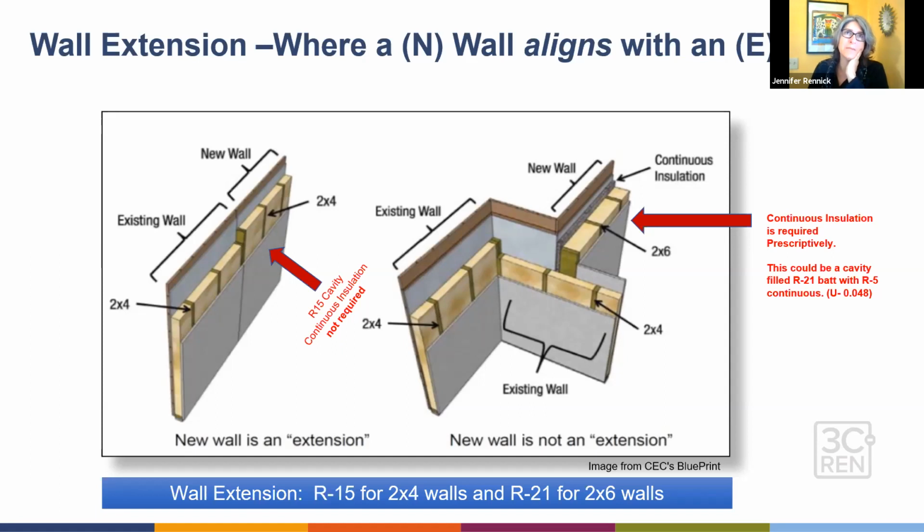And as a plans examiner, I would say that's the one place I've noticed as I double checked Title 24s, where some consultants, I'm not sure they know what they're doing, or maybe they're just really not being careful, but they'll check every box as a wall extension exemption. And that won't be true. It'll only be certain walls.